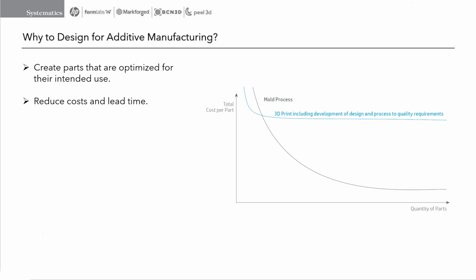The main negative assumption of the flat line curve is that you can go from design to manufacture without any development or setup cost. The truth is that any process will need some sort of development phase in order to meet the quality requirements of the design. During the development phase, both the design and process will always require some tuning. The designer tunes the design to the final fabrication process, and the process engineer tunes the process to the design and its requirements. The beauty of this tuning for AM or digital fabrication is that the tuning can be done digitally and no expensive tooling or expensive reworks are needed.